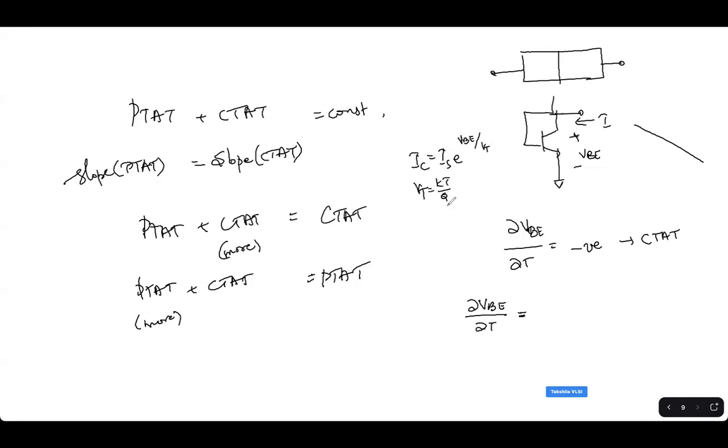It's a temperature dependent voltage, VT equal to kT by q. Now, IS also has a particular expression, a big one. We substitute everything and finally we get del VBE by del T. You need not really remember it all the time, but if you know, it's good. If you do not, it's fine. As long as you understand the current profile, it is good.